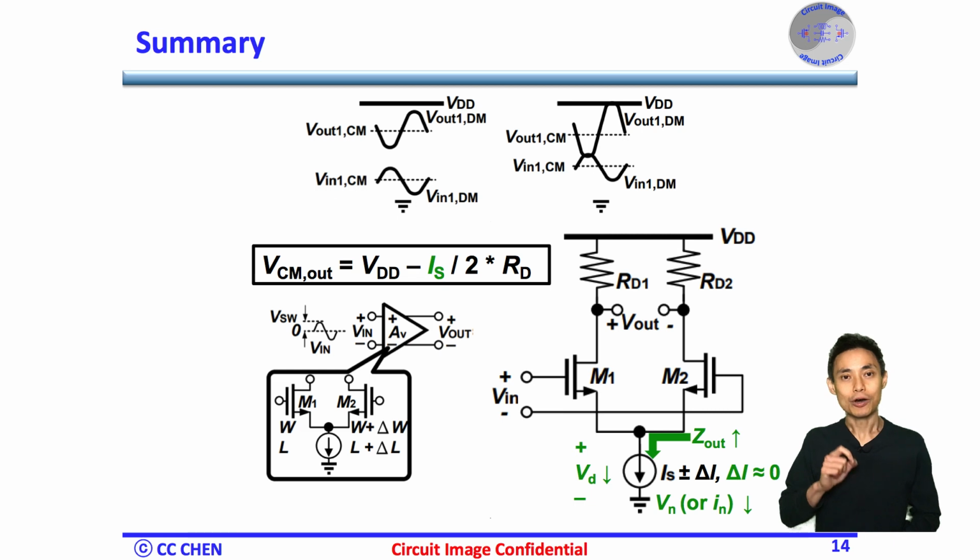Here are the summarized images of why you need a current source. Since the current source will set a DC voltage level properly for either single-ended or differential amplifiers, it's a necessary bias block for all kinds of analog blocks in a serial system. Even though the differential amplifier is preferable to a single-ended one, the current source still needs to be precise, with less voltage drop, noiseless, and infinite output impedance to reduce the impairments of the differential amplifier.